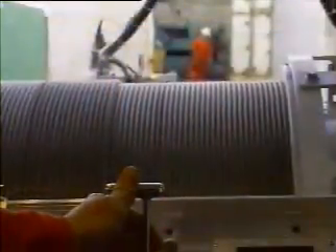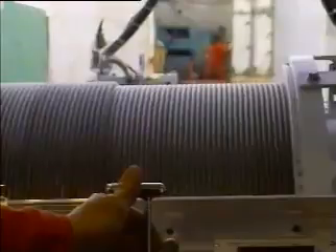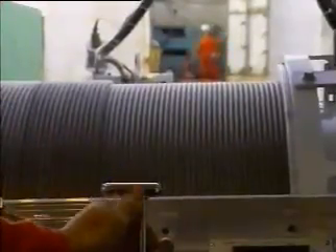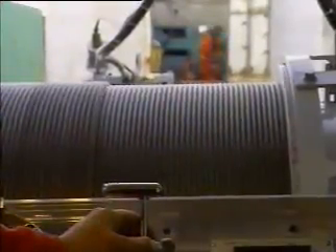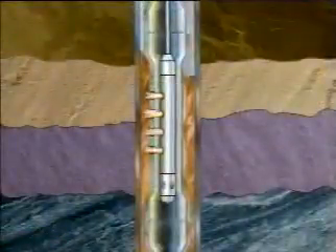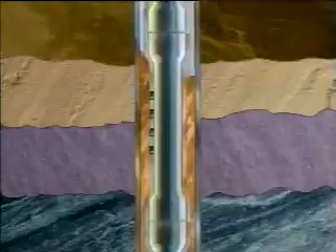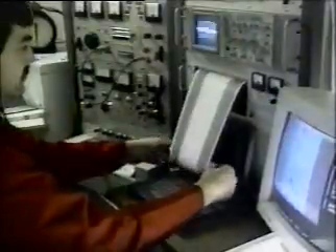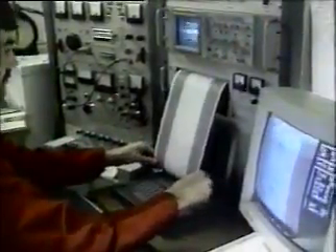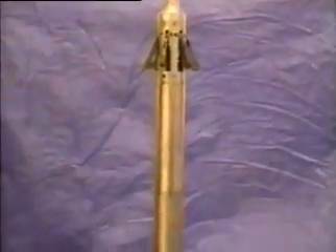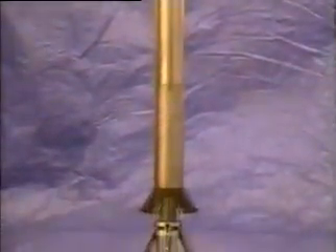In open-hole operations, special wireline tools are used to perforate multiple shots per foot in a string of stuck pipe. Perforations are sometimes necessary to establish circulation to the annulus or spot lubricating fluid to help free the stuck pipe. Other specialized wireline tools are employed by Weatherford operators to aid in the removal of casing, drill pipe, or tubing. Wireline caliper tools are used to measure the inside diameter of downhole pipe.